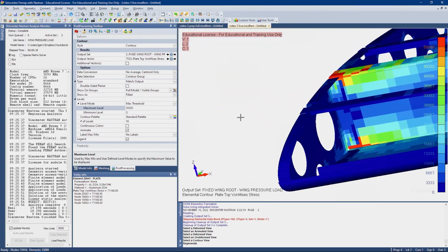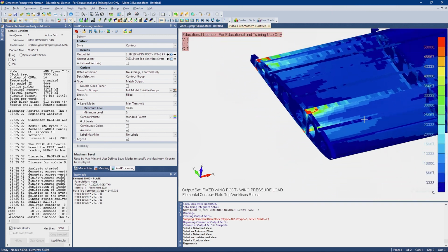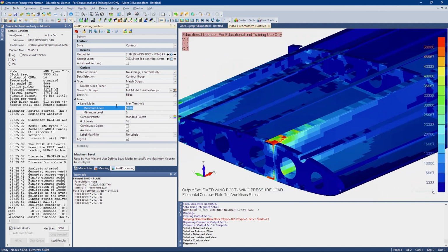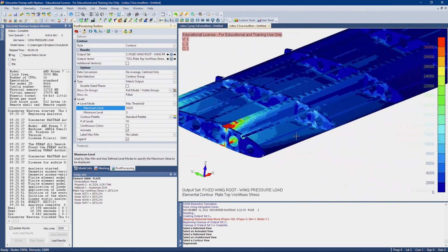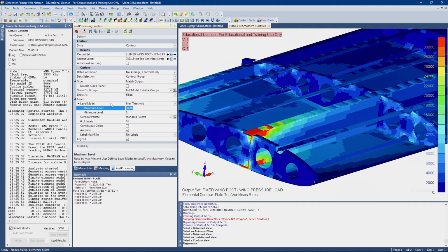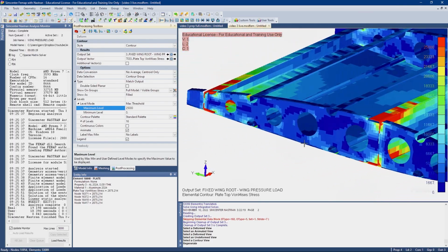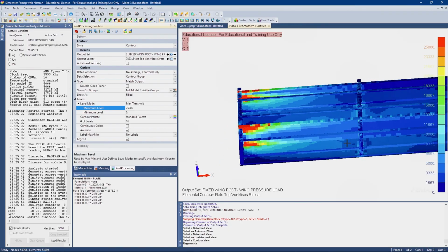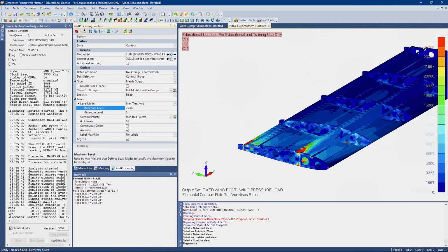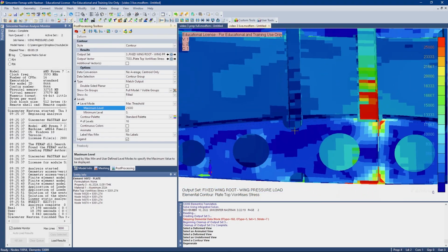So yeah, and you can see that this thin material works everywhere else except the root of the wing. Like if we put this back to 30,000, you can see again, the ribs look good. Like everything looks good. It passes the stress criteria. It's just the wing roots here are way overstressed. So that'll definitely be a future video where we'll revisit this model and design some nice beefy wing roots.